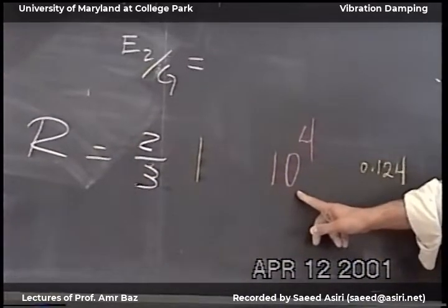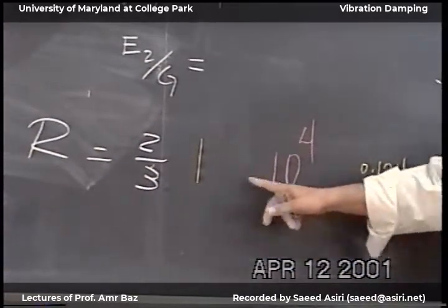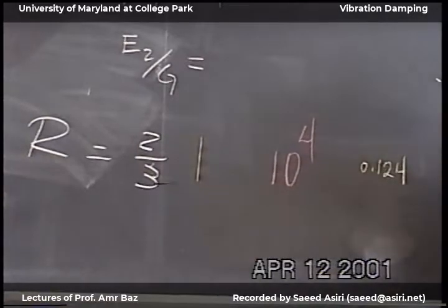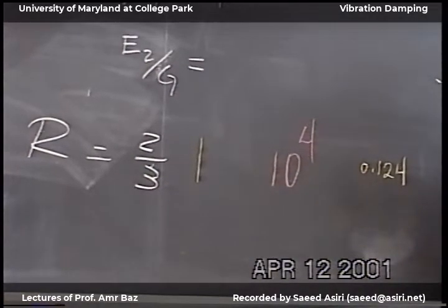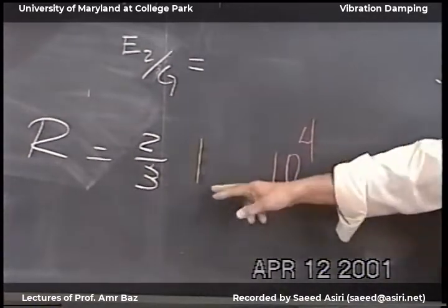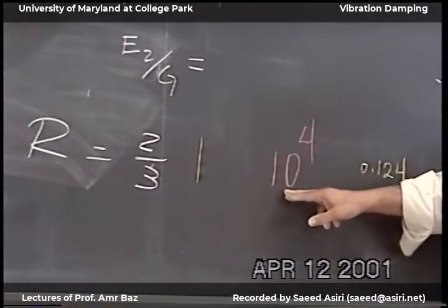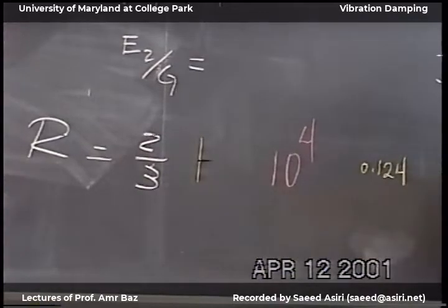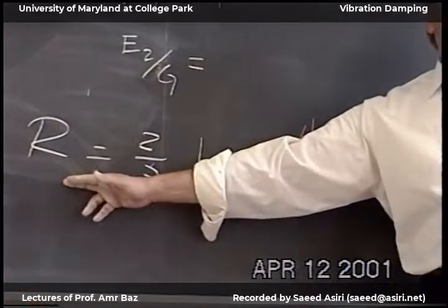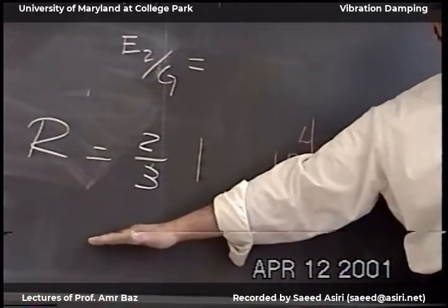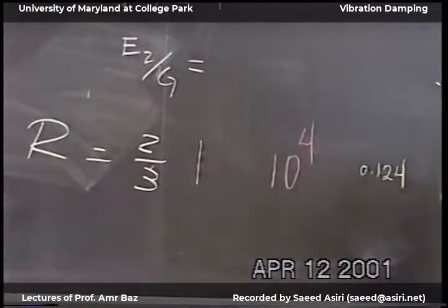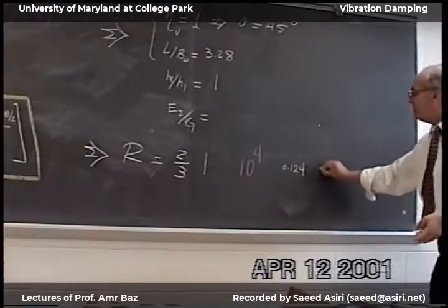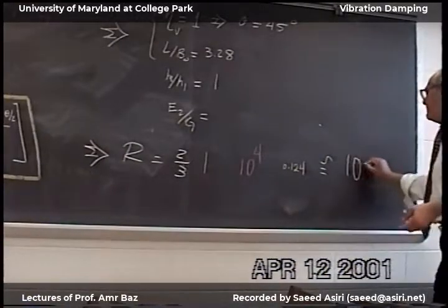1,000 times. Now if you make this very thin constraining layer 0.1 and I have 1,000, the benefit is 100 times. So a very thin sheet of constraining layer makes a big difference in how much energy you dissipate in shear as compared to in tension. So this ratio is approximately 1,000.